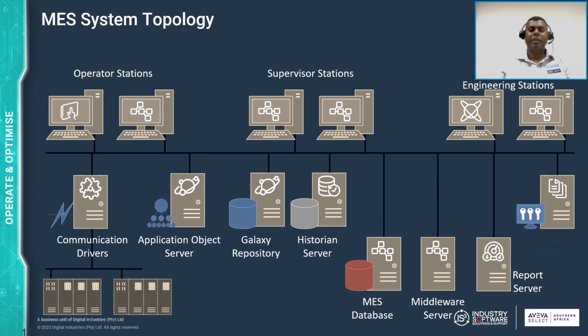Communication drivers. These are computers connected to the control network and running corresponding drivers such as OI server, DA server, or legacy IO servers. A single node can run multiple drivers, but there can also be multiple communication drivers depending on the control network topology. Historian server runs the historian services and hosts the history and alarm databases. Typically, there is only one historian server per project, but there can be more than one if needed. The license server manages the licenses for all system platform components.